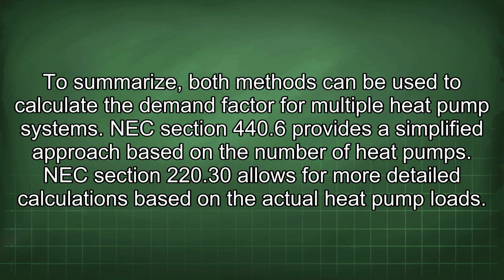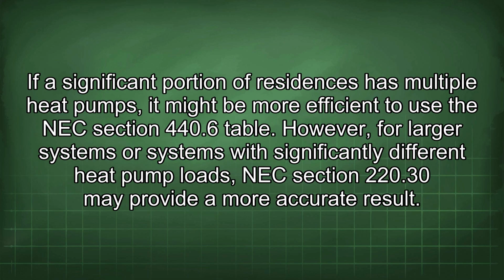To summarize, both methods can be used to calculate the demand factor for multiple heat pump systems. NEC section 440.6 provides the simplified approach based on the number of heat pumps. NEC section 220.30 allows for more detailed calculations based on the actual heat pump loads. If a significant portion of residences has multiple heat pumps, it might be more efficient to use the NEC section 440.6 table. However, for larger systems or systems with significantly different heat pump loads, NEC section 220.30 may provide a